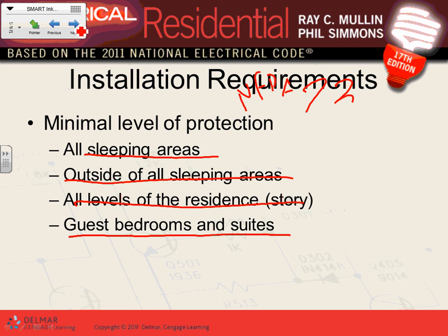In our area, we're not doing a hotel or motel, are we? No, we're doing an apartment building. So you're going to put it in every bedroom, and in every hallway in the front of the bedroom, and you have to put it also on every level if you have multiple levels. Cool. Can I have thumbs up, Chad?